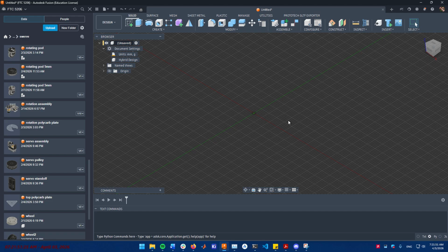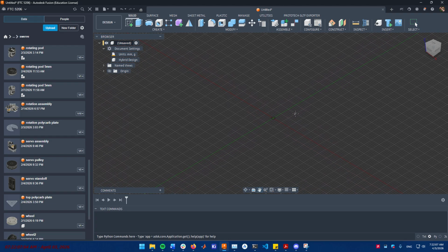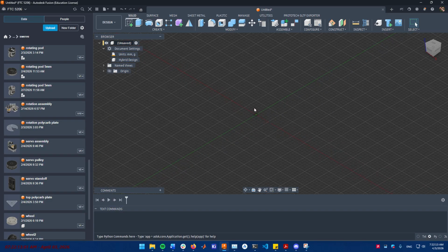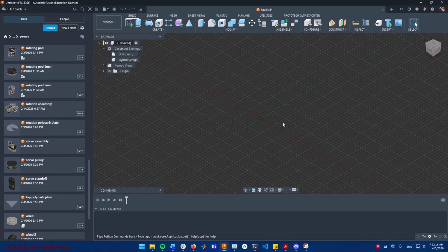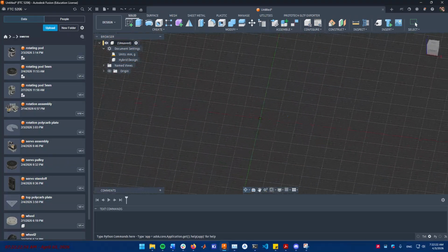So let us begin. First, when you load in, you see this screen, but that's not very helpful. You have to be able to move, right? So the default keybind for panning is the middle scroll wheel. And because of this, I recommend you all get a 3-button mouse at least. And to zoom, of course, is scroll out and scroll in. And orbit is if you press shift and the middle scroll button, that will rotate along the center.